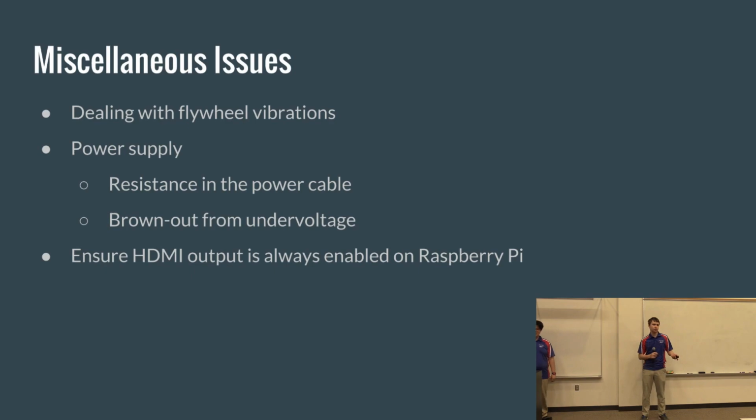If you have a Raspberry Pi wired up to a monitor, you may notice a little square in the top right corner that's rainbow colored. That's their symbol for under voltage. It's a little counterintuitive, but that's what it means. If you see one of those, you want to look into your cables, take a voltmeter or whatever, and make sure you're getting the right voltage, because that will cause you issues. It can corrupt your file system just like shutting it off improperly.